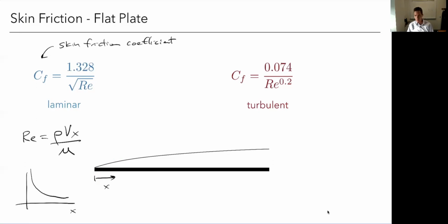So you often see that, right? Smoothing out the leading edge. And ideally, sometimes, we'll use layup or a laminate or something to get a smooth surface everywhere. But if we can't, and it's going to be tape, which is going to be heavier, we'll generally just put it towards the leading edge.